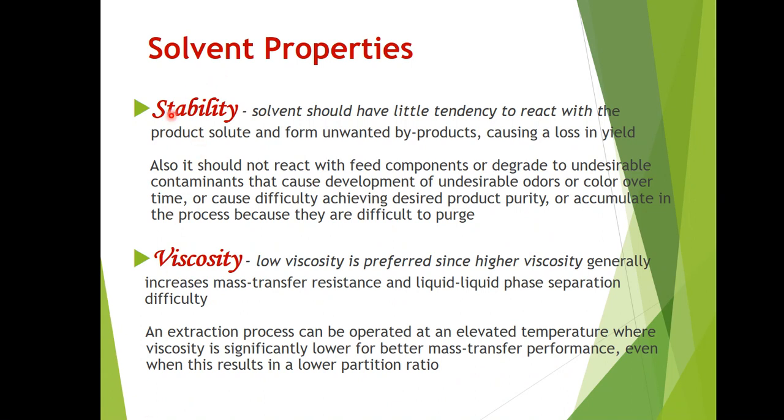Stability has to do with your solvent having little tendency to react with the product solute and form unwanted byproducts. We don't want any reaction to happen in pure liquid extraction. It is a simple physical process that should not have any chemical reaction occurring. So this is a requirement.